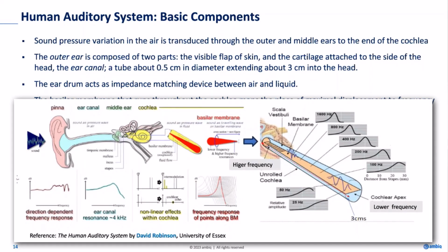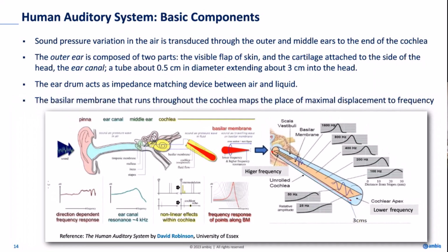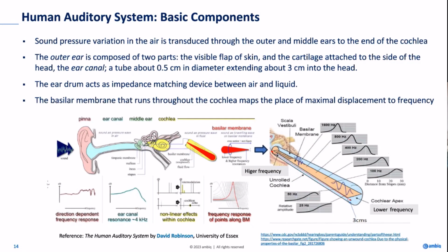We'll come back to this one when we talk about the perceptual model, auditory model, or when we'll be designing a subband system. Just to give a brief overview here: our mind perceives sound not linearly, but logarithmically. At lower frequencies, you need more loudness, but the frequencies are closer. At higher frequencies, you need less loudness and frequencies are spread out. This is the reference we have taken it from.